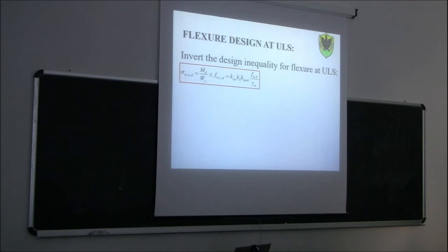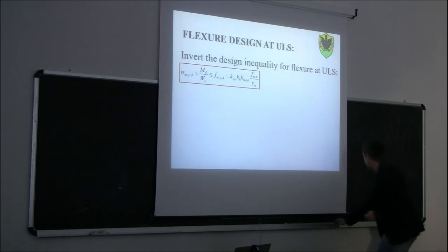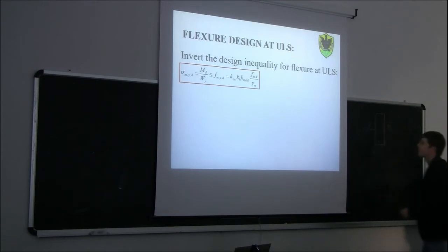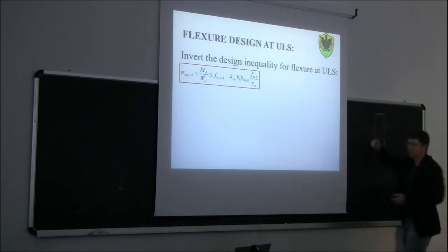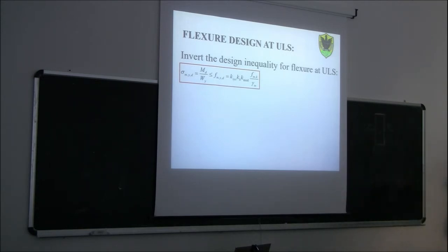So we have the cross section, y is the horizontal, this one basically. And d is the design value of the stress, meaning the value of the stress in the most stressed fiber due to the design value, which is the ultimate limit state load. Okay? So this is M_d.